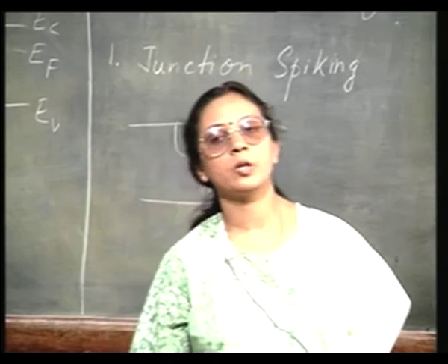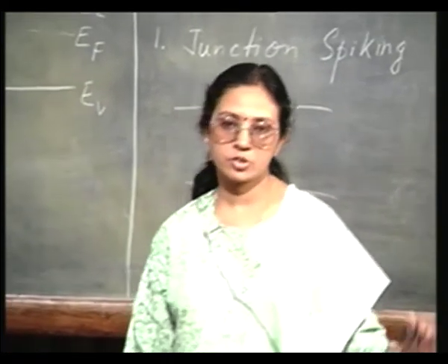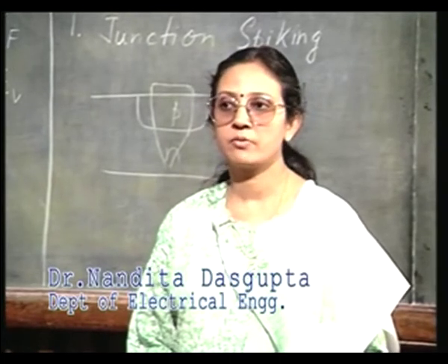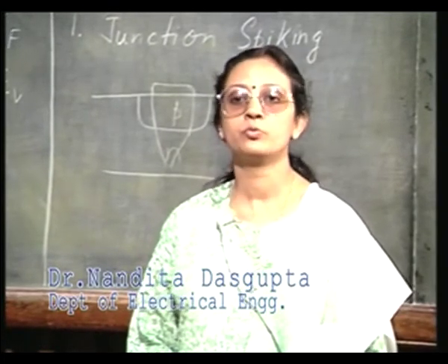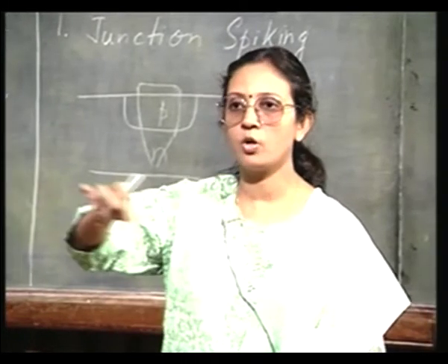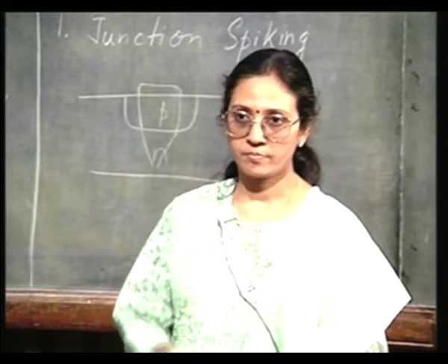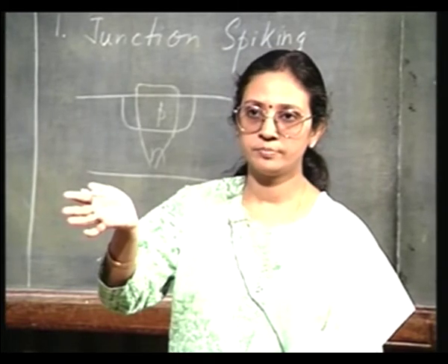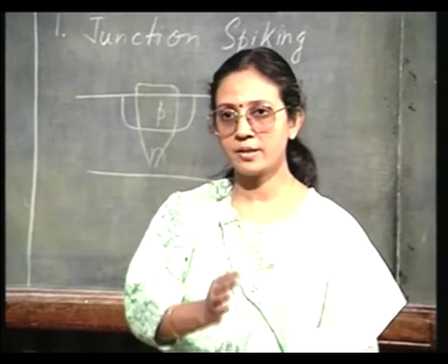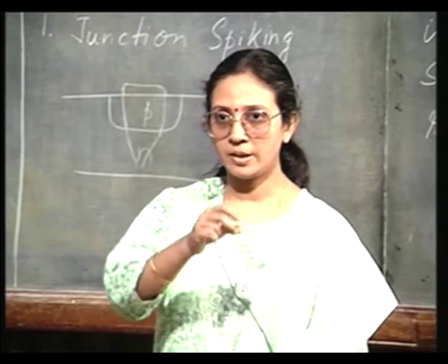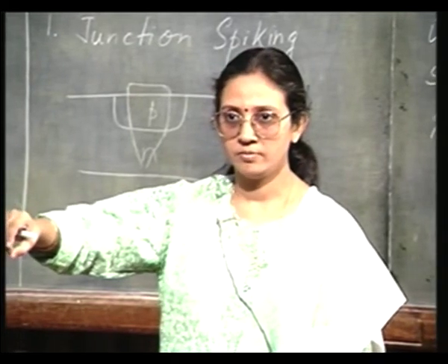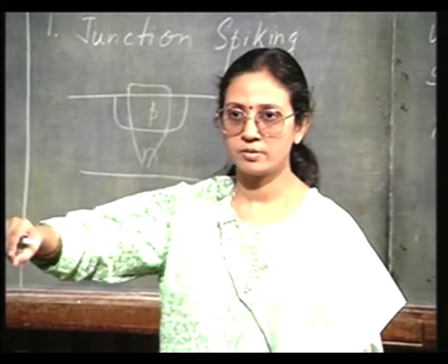The other severe problem associated with aluminium metallization is electromigration, where under a very high electric field the metal layer starts to move. The aluminium metal itself starts to move. So, suppose you have a long line of metal along the direction of the field, it starts to move, so that you have a break in the metal line. The metal from that point has got transferred somewhere else following the direction of the electric field.